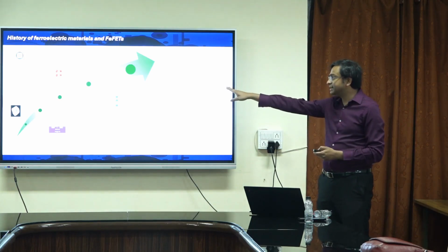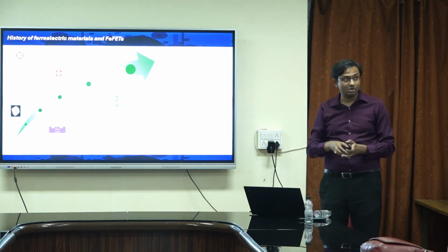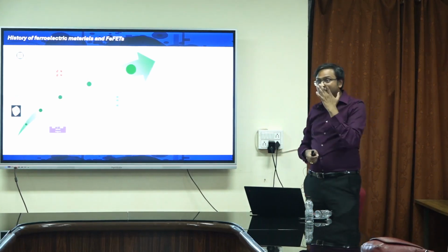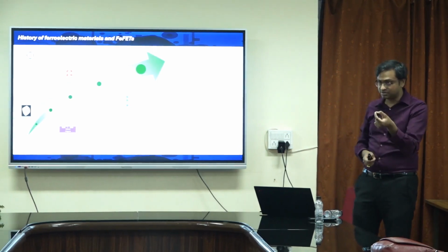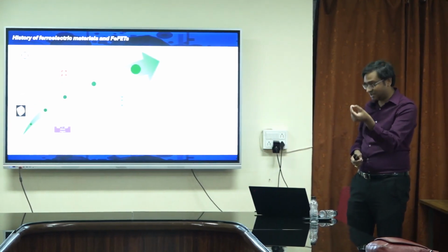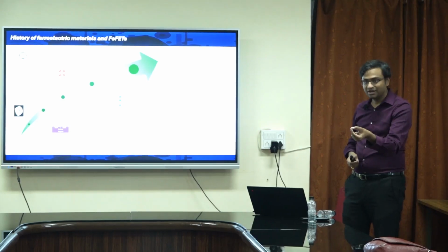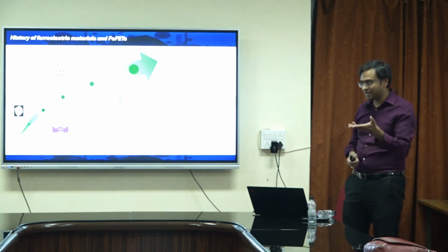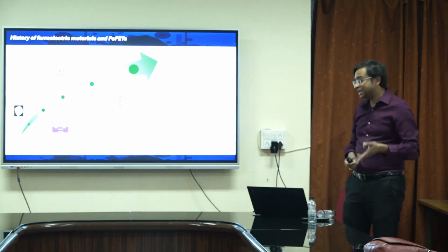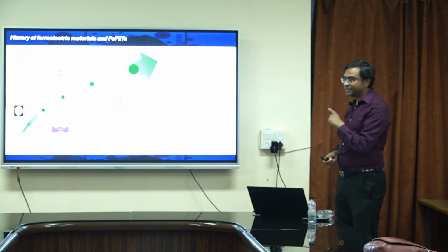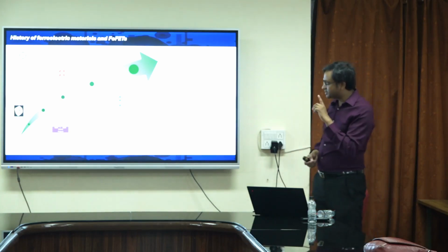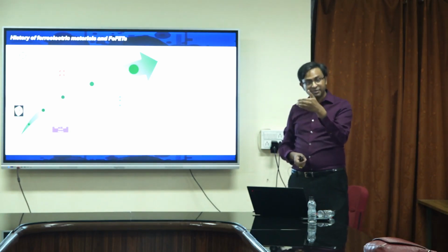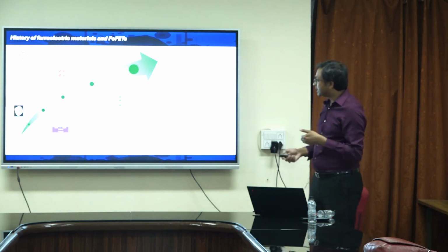And then more recently, people have discovered that if you take hafnium oxide, which we were talking about for the high K, right, which we could integrate with silicon, people were able to show that hafnium oxide, when doped, may actually become ferroelectric. Right? So now that integration challenge is mitigated. You see, because I can do an ALD process to grow hafnium oxide, dope it, it becomes ferroelectric. So that is a big field right now. Generally, zirconium doped, silicon doped, or aluminum doped hafnium oxide becomes ferroelectric. Okay? So that's very interesting.